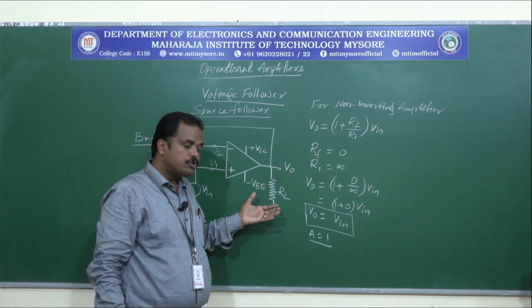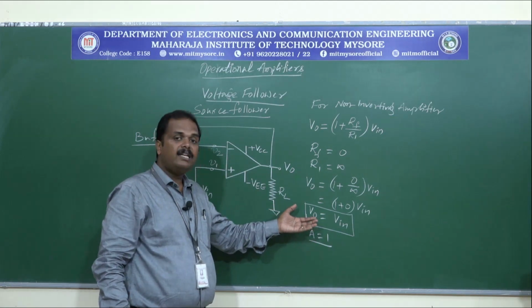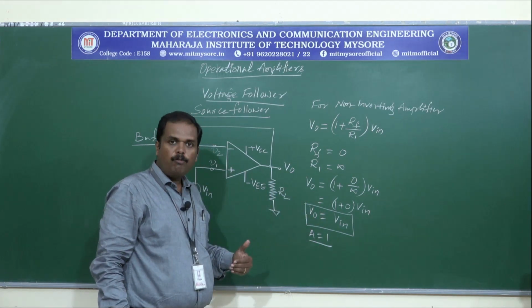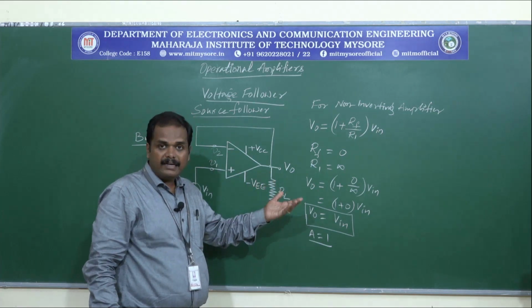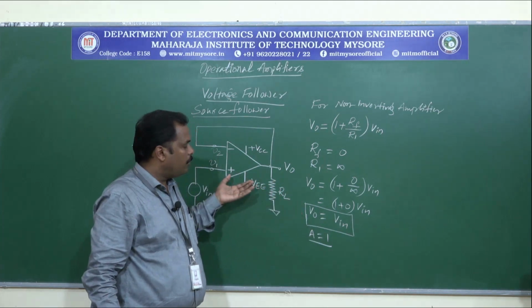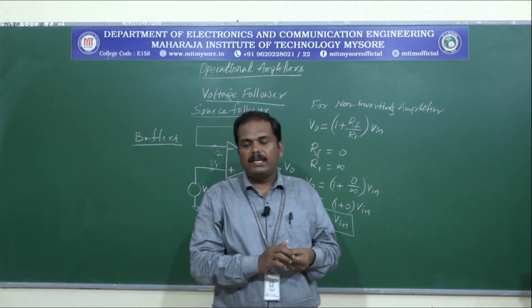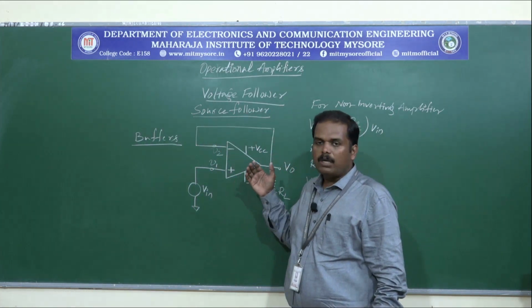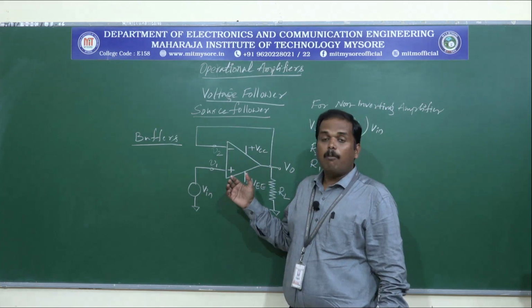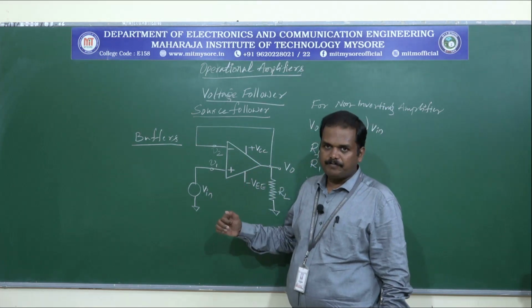So this can be used where we have to maintain the voltage same as the input but want enhanced current levels, then we will be using these buffers. I mean, we can use this voltage follower or source follower as buffer circuits.